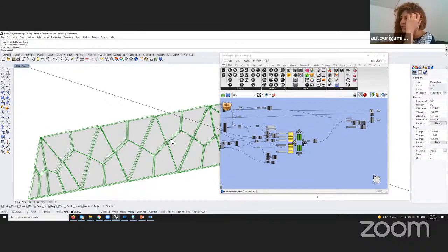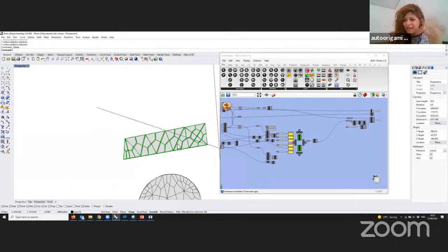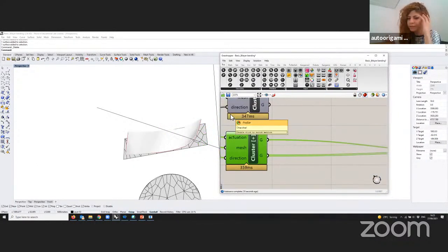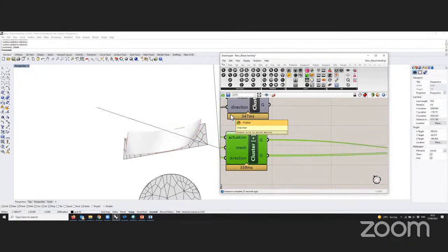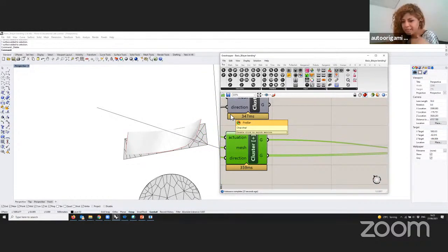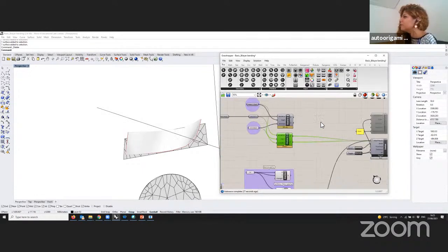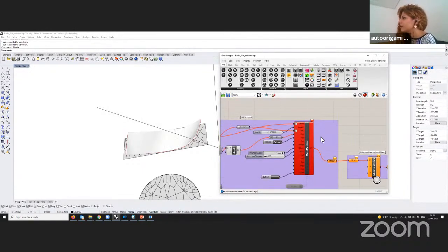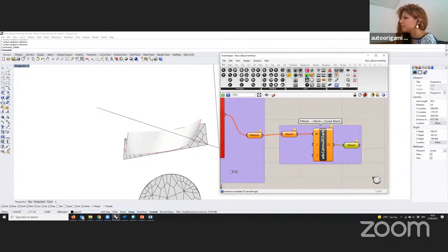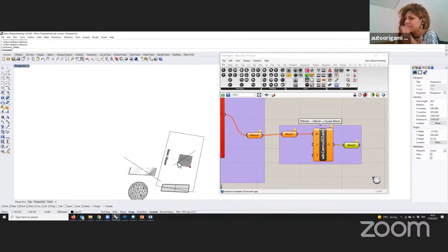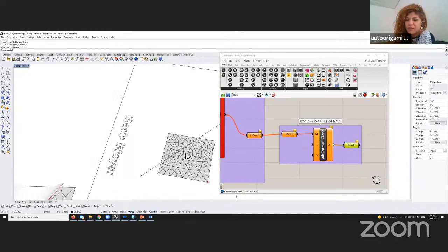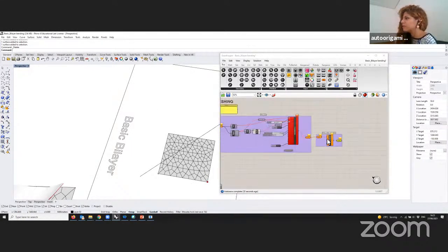The thing we want is for these to be absolutely random, without any special directionality or any special form, so that overall they work together as this bilayer structure. If your meshes are all aligned and then they scale in one direction more than the other, it messes things up. So we use this meshing on top so that we can have a nicely divided mesh overall, and also not directional.